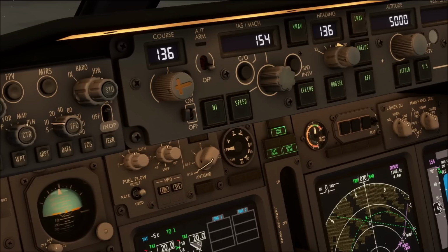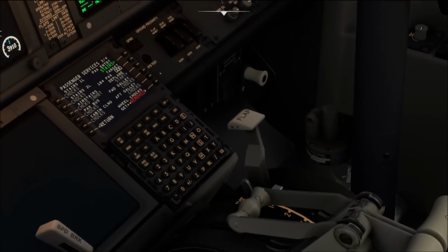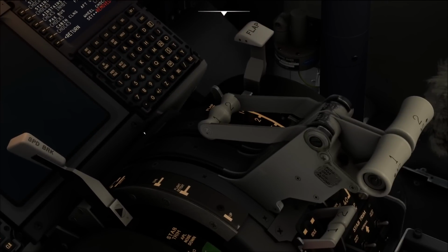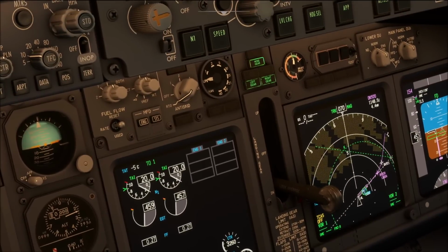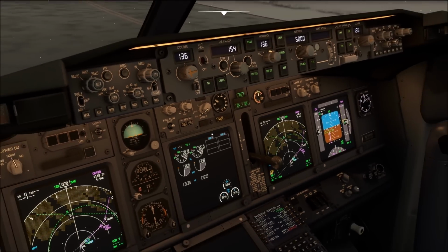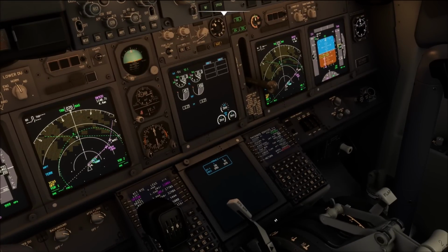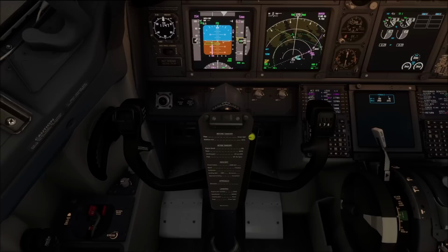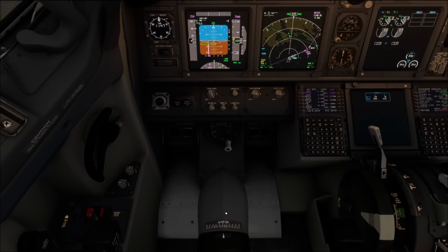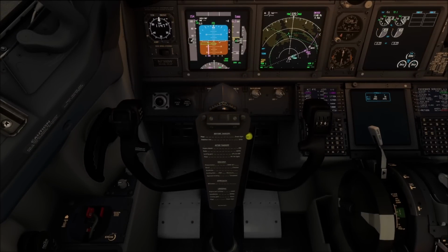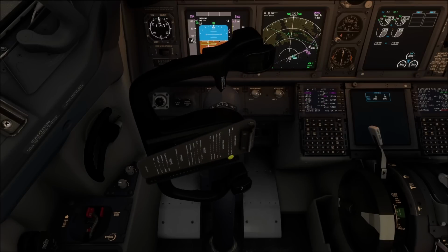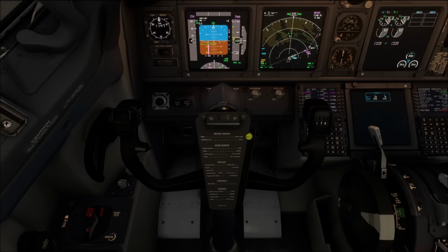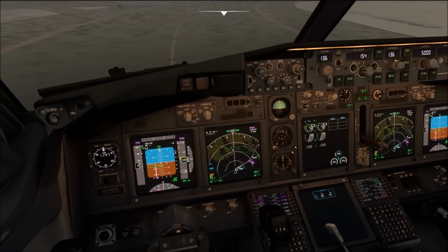Okay, we've now ensured that our flaps are fully operating, so let's select the takeoff flap position, which in our case is going to be flaps 5. At this point you would also carry out the flight control check and be aware that the control column forces might be increased over here. So if your airplane has the flight control display, do bring it up. If not, like the majority of 737s, which do not have it because you have that mechanical connection, let's go ahead and check our flight controls. Full up, full down, neutral, full left, full right, neutral, and the rudders, full left, full right, neutral.